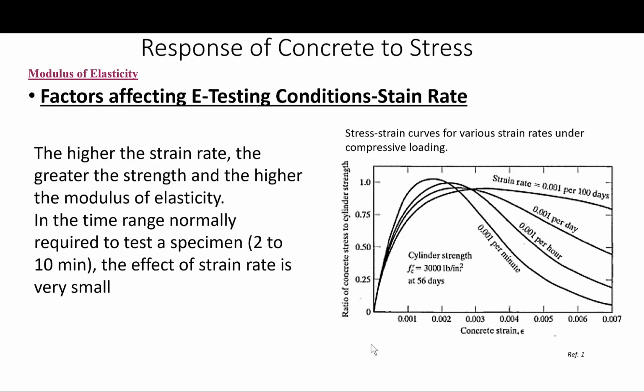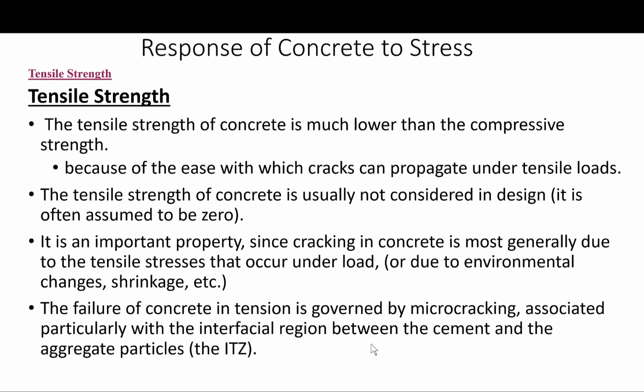Okay, so these are basically the factors that impact the modulus of elasticity of concrete. We said the strain rate, the aggregate, the water cement ratio, which is basically the porosity of the cement paste. Okay, let's now move on to the next subject, which is the tensile strength.